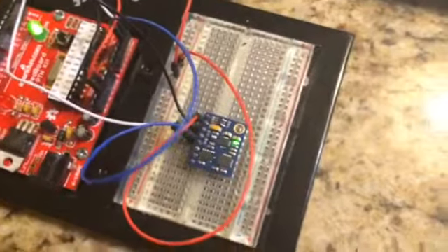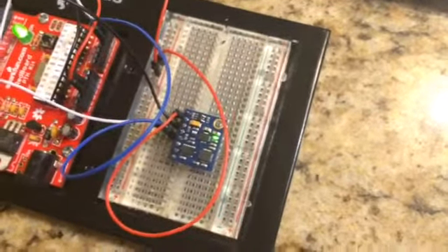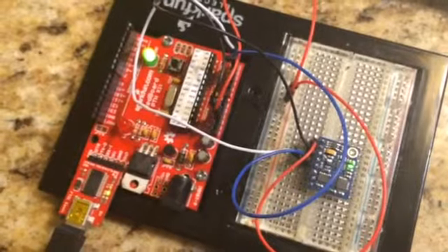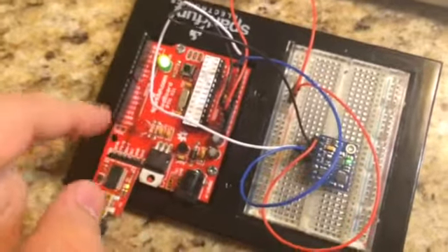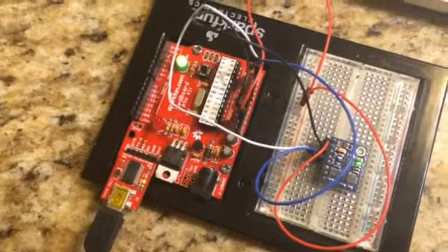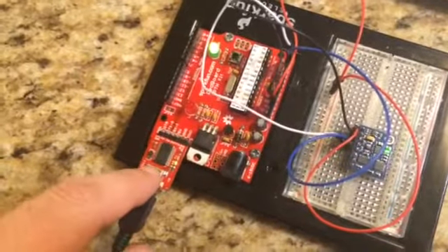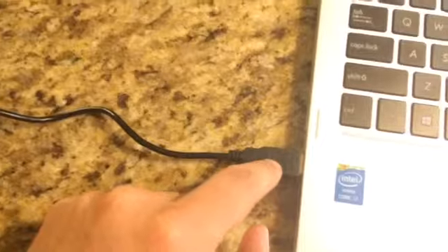And what I've done is, through just standard I2C, this Arduino board here is taking the information, converting it into an object notation, kind of like JSON, and via the FTDI adapter here is running through this cable into my USB port on my laptop. And I've created a program in Processing that graphs, at this point right now, just the X and Y axes acceleration.